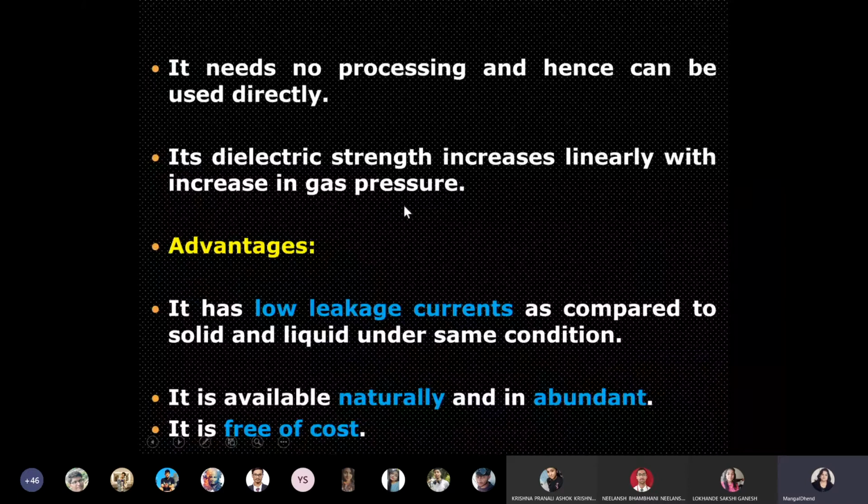Then how will breakdown take place? If the number of gas molecules is more, the breakdown strength will be more, meaning breakdown voltage will increase. Why? That we will discuss when we complete the ionization process. By that time, just keep thinking about what might be happening if gas pressure is increased, and why dielectric strength goes on increasing.